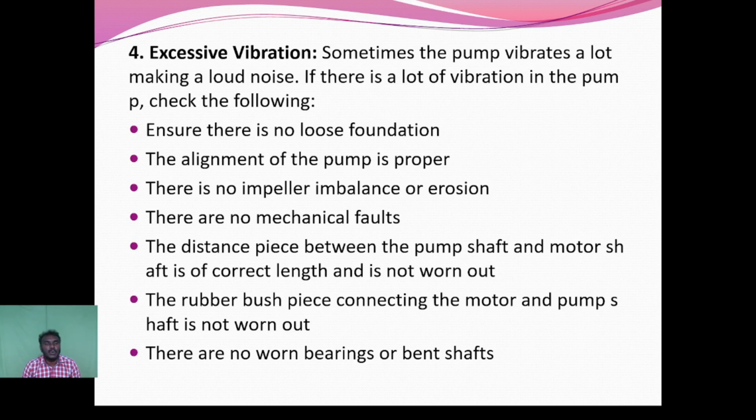There is no impeller imbalance or erosion. There are no mechanical faults. The distance piece between the pump shaft and motor shaft is of correct length and is not worn out. The rubber bush connecting the motor and pump shaft is not worn out. There are no worn bearings.